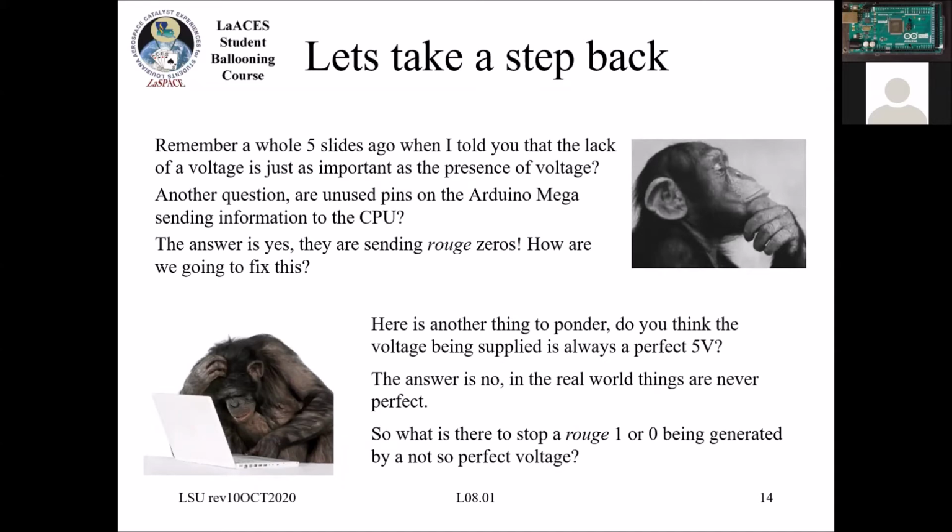So, just like we said, the zeros for an Arduino is a unipolar voltage, so it has zeros and ones. So when the voltage is low, it's considered a 0. But we probably want to know the difference between I have a 0 at an input versus I don't have anything connected to an input.